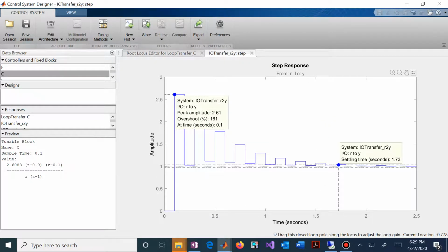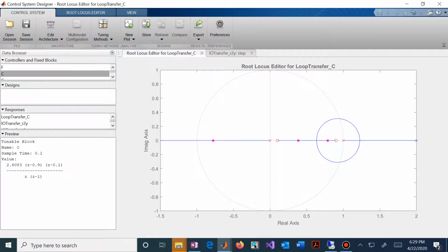now that pole at -1 gives us this ringing behavior. We still settle, but you may not like this dramatic change up and down, up and down, up and down because of this pole. You say, well, these are better locations for my modes in the positive real axis, but it's now giving rise to this negative pole location. It's stable, but it may not be what we want.